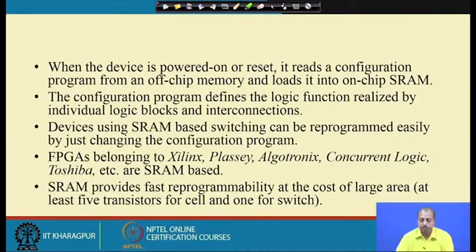Devices using SRAM based switching can be reprogrammed easily by just changing the configuration program. That is very good, because normally when you are in the early stage of your design, there will be design bugs. If you go directly for chip fabrication, then there is a possibility that many of those bugs are not detected at the time of design.